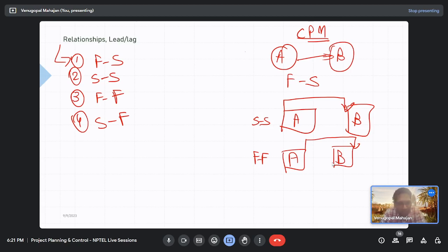Let's suppose there are 20 beams. But in some cases, sir, it is allowable. As you are saying, 20 beams. So if reinforcement of 10 beams is completed, then we can start our concrete pouring for those 10 beams, and partly we can do the rest of the 10 beams after the reinforcement work is completed.